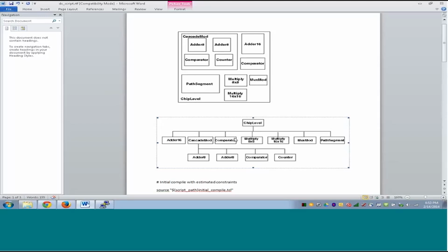Plus, you will obviously do pre-layout STA and then post-layout STA at chip level. Now, if you see any interface that is violating and not optimized properly, you can feed this back to the respective designer and ask them to correct their port constraints, their input and output delays. This is how it works in industry.